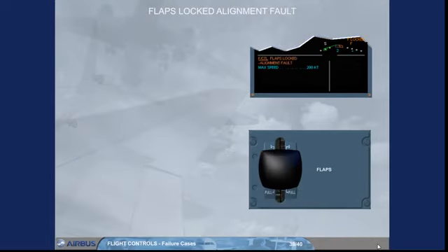The flaps have a flap disconnect detection system. This system detects attachment failure and inhibits flap operation to limit further damage. In this case, you will get an alignment fault. The procedure is similar to the flaps lock procedure seen previously.